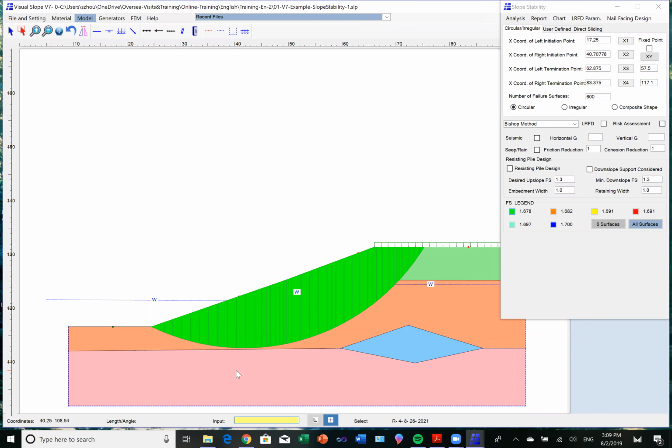The way to find out is, if the failure surface is far away from the point you defined, it means you found the most critical failure surface. On the other hand, if the failure surface is very close to this point, it may go further and there may be a more critical failure surface, then you should have moved this further away. Let us search in this way.